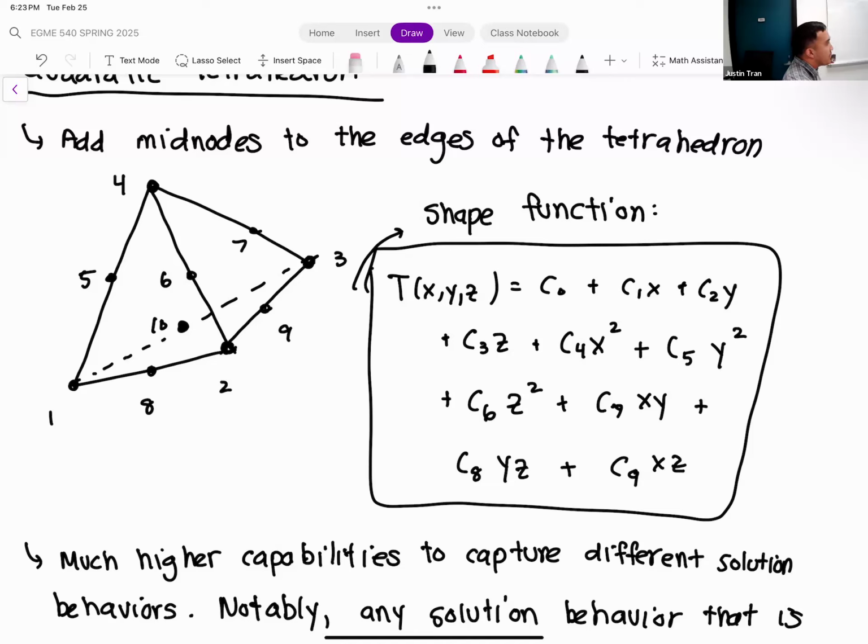But there are ways to mitigate that as well, which I think ANSYS does, although ANSYS is proprietary with a lot of their algorithms. Generally we want to avoid that, and you can do that a lot of times by smoothing your starting geometry, so taking your CAD file. A lot of times those skewed elements appear at sharp corners, so just doing something simple like adding fillets to your geometry, or making it so that you don't have two parts that are awkwardly attached together. We'll talk about that a lot more as we get to more advanced meshing. But sometimes also it's just making the elements smaller that will help to not skew the elements.